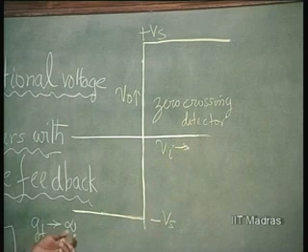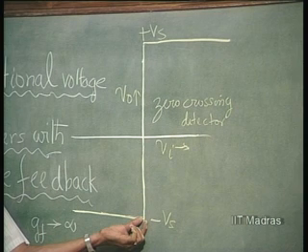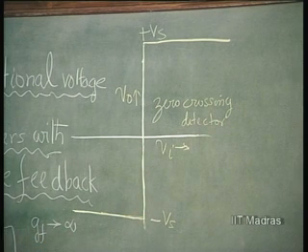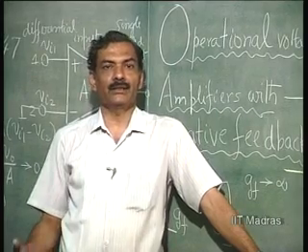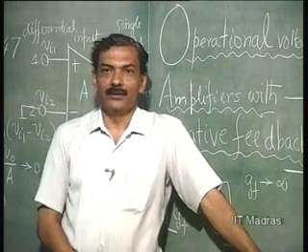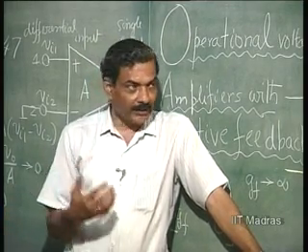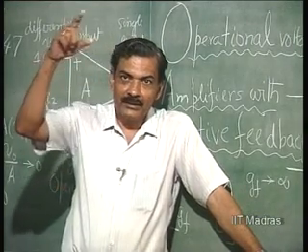So, it tells us to a great degree of accuracy when exactly the input voltage crosses 0. Where do we use this zero crossing detector? Normally, when we design electronic switches, these switches tend to operate when a power line is being switched, let us say. When the power line is being switched, we would like to switch it exactly when the voltage is crossing 0.